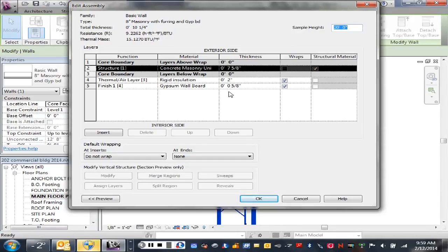Okay, when we get to the top of this exterior wall, like I just talked about in the levels, we're going to switch to a thinner wall, right? So a couple ways of doing that. We can put in a reveal, right? So that 8-inch now becomes a 4-inch or whatever it has to be. Or we can bring our 8-inch masonry wall up to a height of whatever it has to be, 10 foot or whatever, and then on top of that put a different wall.